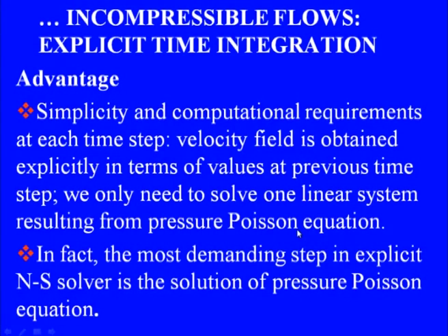And remember, the only system of equations which we have to solve is our pressure Poisson equation. That makes this step the most demanding step in an explicit Navier-Stokes solver, and because of this, the solution of the pressure Poisson equation is still one of the most challenging research areas at the moment. People are trying to develop faster and faster solvers, what we typically call fast Poisson solvers,